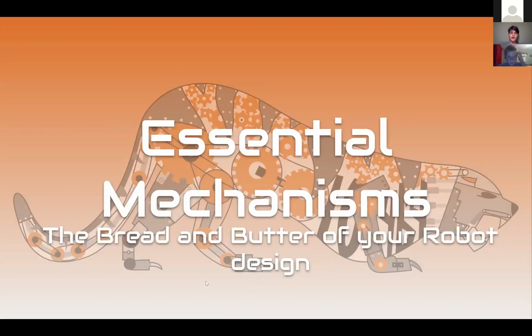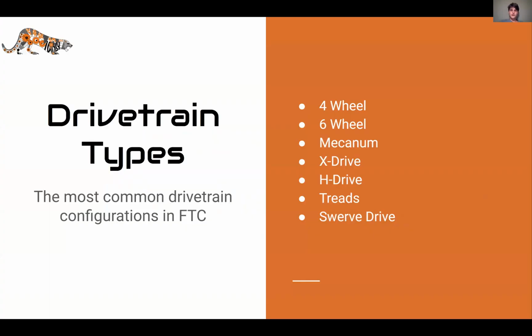Specifically today, we're going to be talking about some of the essential mechanisms, some stuff that will be very useful for you when you're designing your robot as to what it should do on the game. So the first thing we're going to talk about is the fundamentals of any robot, which is your drivetrain, which is the wheels that your robot will be based on. There are a few different variations that we will go over. The ones that we will be talking about will be the 4-wheel drivetrain, the 6-wheel drivetrain, the Mecanum drivetrain, the X-Drive drivetrain, the H-drive, the treads, and the swerve drive.